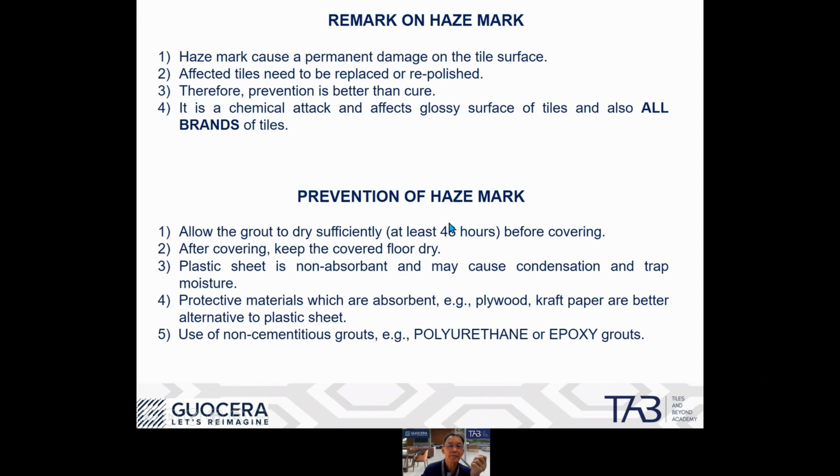Now, to prevent haze mark, what we can do is to allow the grout to dry sufficiently, at least about 40 hours before covering up. Because if the contractor covers the floor too early after grouting, the grout needs to evaporate, and when it evaporates, moisture comes out. This can cause the reaction. So the grout needs to be allowed to dry for at least about 2 days before covering up. And after covering up, the covered floor needs to be kept dry. Do not allow water to go beneath the sheet, because when you have water, it causes this reaction.